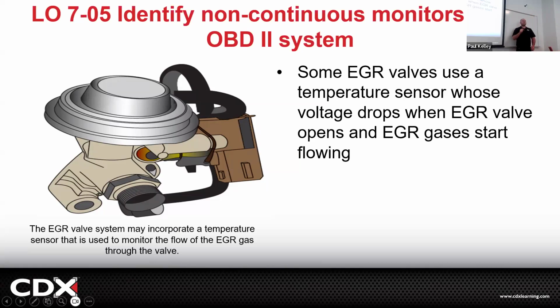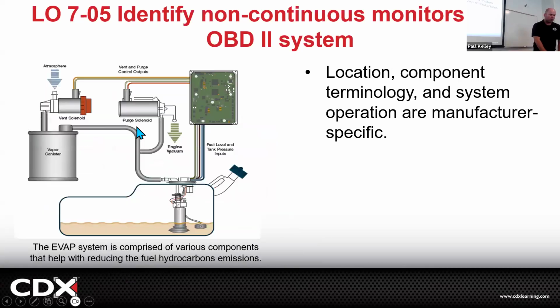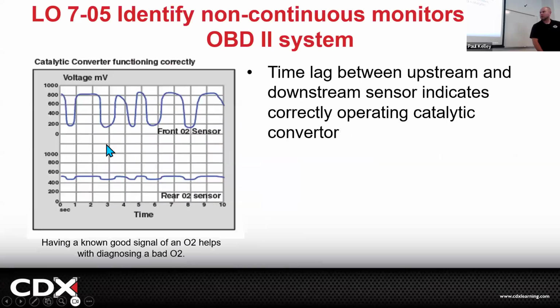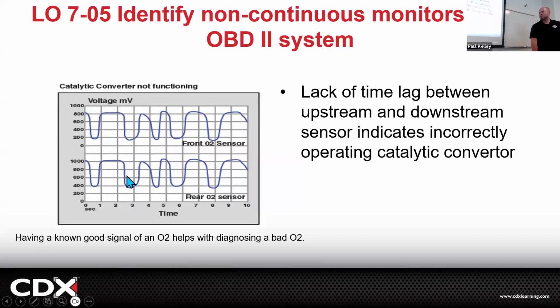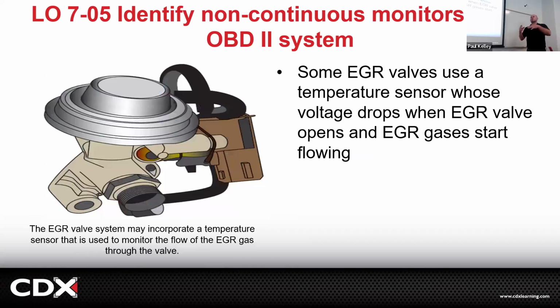working. And if the EGR is blocked off, you're going to get a code set for EGR performance because it doesn't see the increase in temperature, or it doesn't report back that the valve has moved because the valve is in the trash, or it doesn't report that your catalytic converter is being cleaned up like this because it's hollowed out like my dad's, which would look like this, right? So a lot of what these sensors are doing is reporting that the emission system is working the way it was supposed to, the way it was certified, the way it was sold and federal government approved.